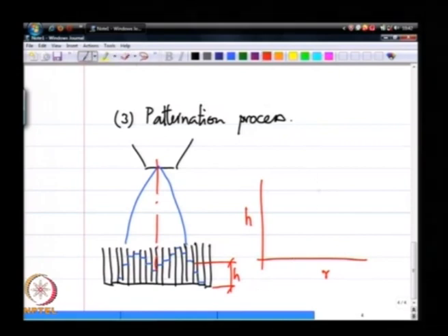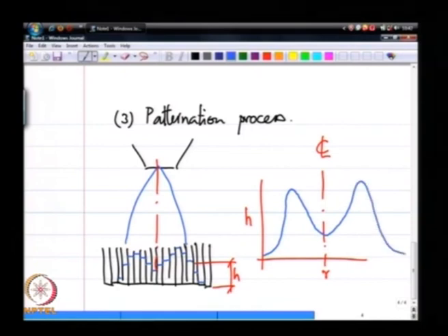Okay. So, in other words, I have to figure out some way to convert an otherwise blurred edge into a quantitatively repeatable sharp edge, and this is a case where I take this series of tubes, insert them underneath the spray and collect volume in these tubes from the spray over a fixed period of time, and that gives me the tube levels.